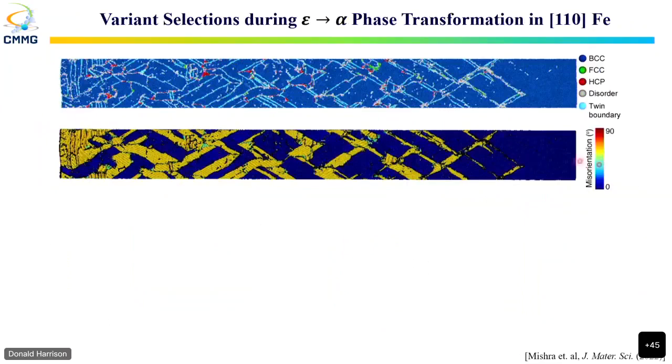You can look at the misorientation of this microstructure, which shows a whole bunch of coherent twin boundaries. If you just look at this microstructure, you have no idea which one is a twin. Is this region a twin, or is that region a twin? We then go back to the orientation analysis and say, okay, this is all the old parent orientation that was already there. So the only things that have changed are these ones over here, the yellow ones. Now, is this one type of twin?